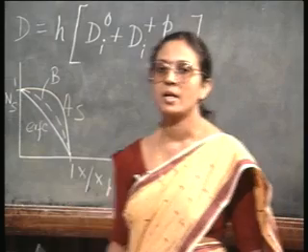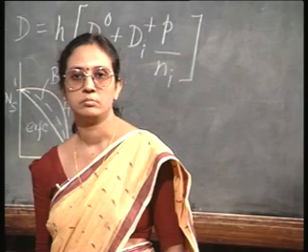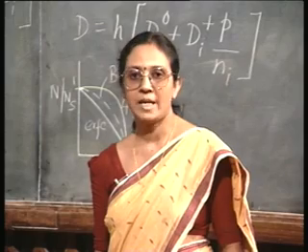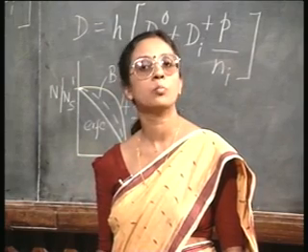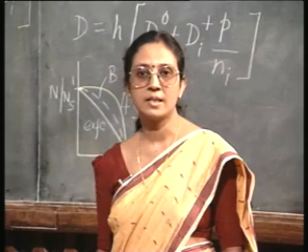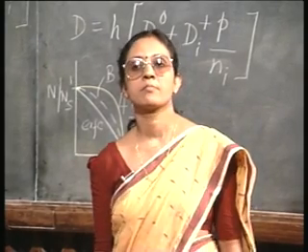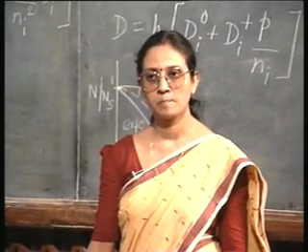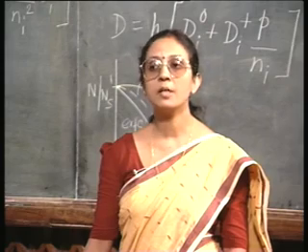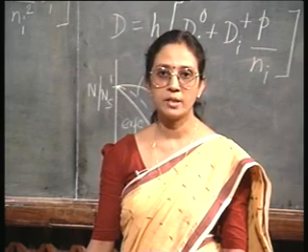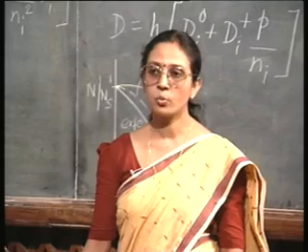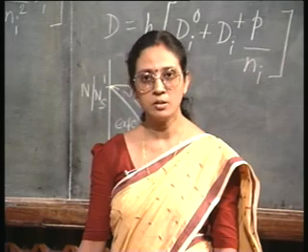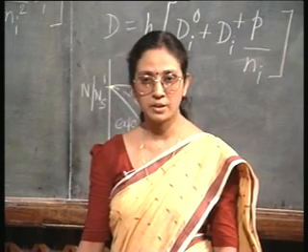Consider an NPN transistor. Okay. Let us say NPN, therefore, the base is boron doped, and let us say that the emitter is doped with phosphorus. So, you know that after the base diffusion we have to carry out the emitter diffusion. So, when we are doing the emitter diffusion, the base should also get further deeper diffused, but this deep diffusion